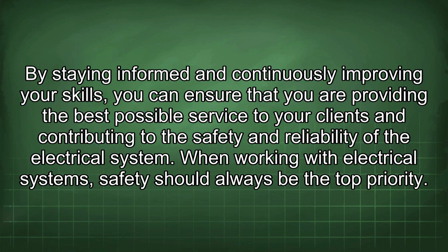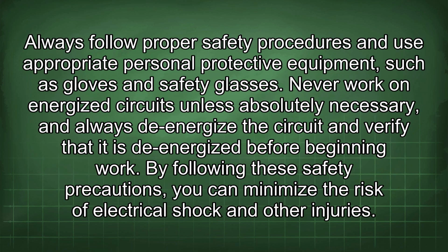When working with electrical systems, safety should always be the top priority. Always follow proper safety procedures and use appropriate personal protective equipment, such as gloves and safety glasses. Never work on energized circuits unless absolutely necessary, and always de-energize the circuit and verify that it is de-energized before beginning work. By following these safety precautions, you can minimize the risk of electrical shock and other injuries.